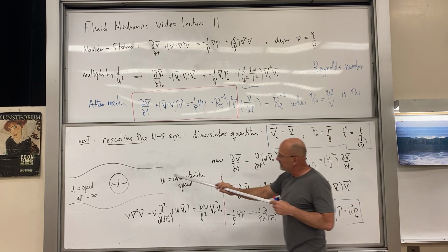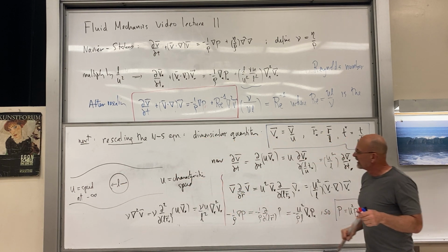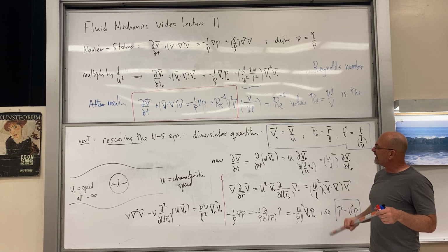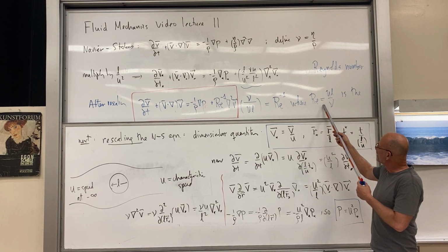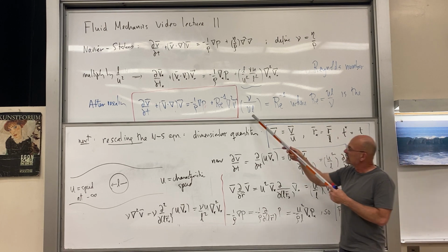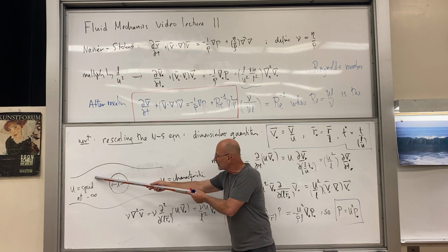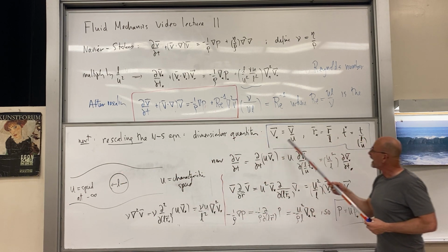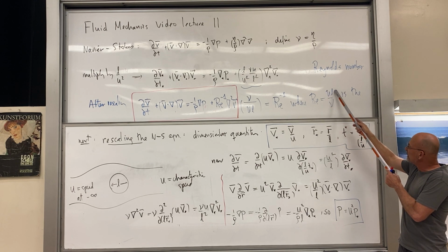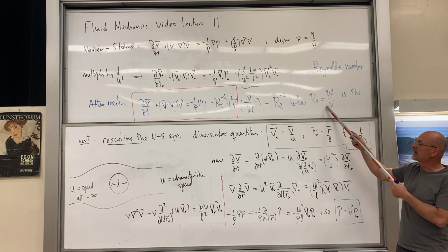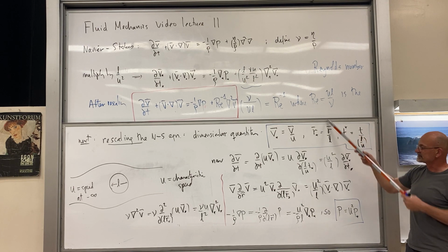Suppose we go back to a flow pattern like this here, then as long as the Reynolds number is the same, we would have the exact same mathematics. So we would have a universal flow pattern as long as this combination, this speed, this dimension, this viscosity, give us that same number, Reynolds number.